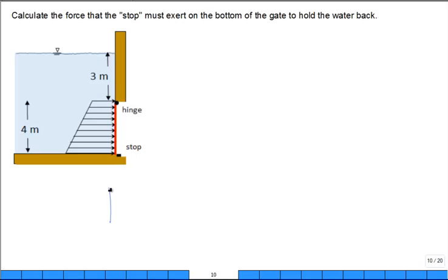So if we do a free body diagram of the gate, we have the hinge, and I'm just going to show it at point A, A_y and A_x. Those are the resultant forces that act on that hinge to hold the gate top right there at that location. We're going to replace the distributed load by a point load, F of R, the resultant hydrostatic force. It's purely in the x direction, and we have to know its location. We're going to have to work on its location. True? And the stop has a force S to hold it in place. True?